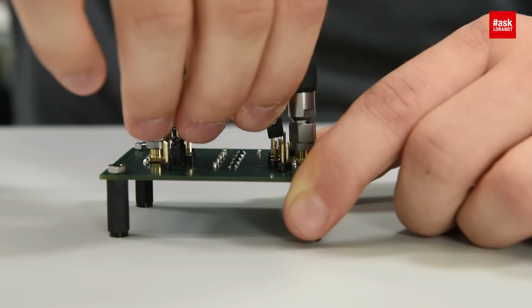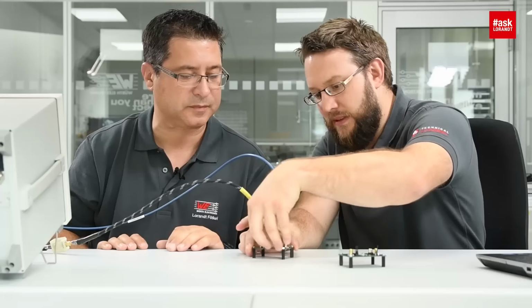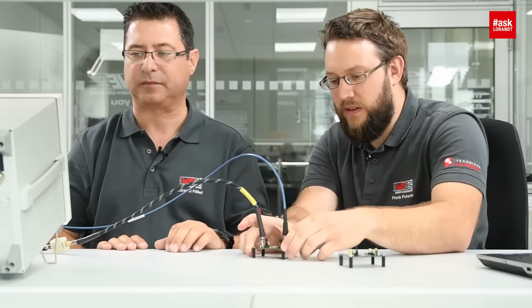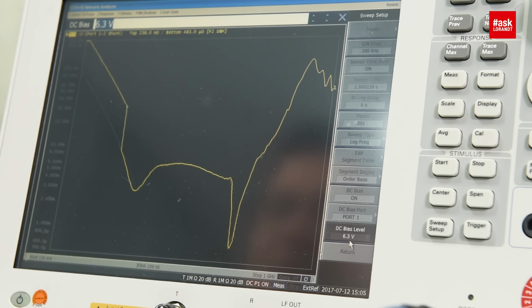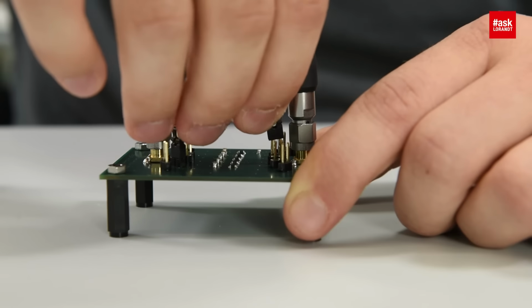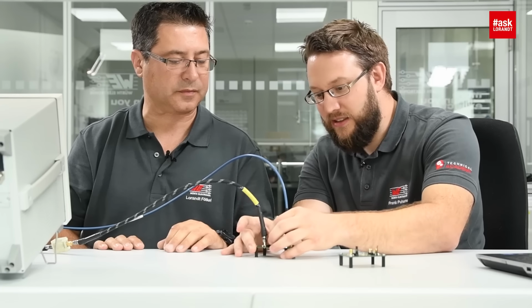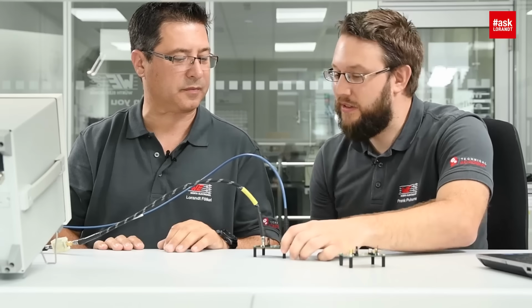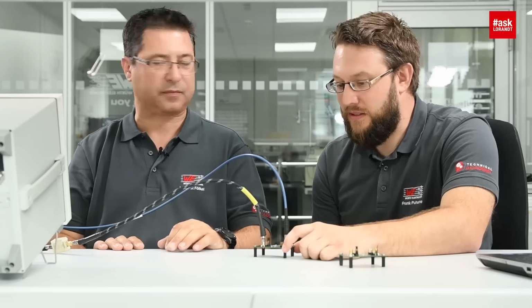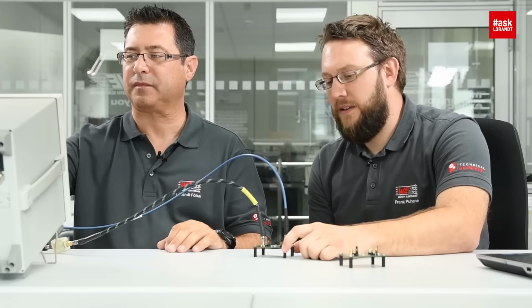Next one is a 22 microfarad capacitor, also X5R, 6.3 volt. Here we also see the massive influence of the DC bias, because it's also a high capacity value. Now we use the third filter. The ferrite stays the same, of course, and the capacity value is about 10 microfarad, also class 2 ceramic X5R. Let's check the DC bias behavior.